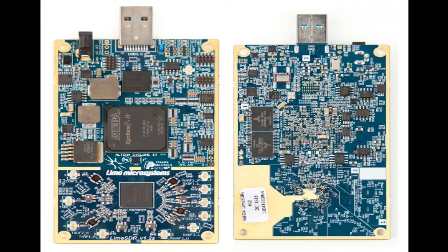It has a lot of other nice features that the Express doesn't have. For example, receive as well as transmit channels, and two of them, and it also has anti-alias filters which are programmable within the chip itself, so we won't need to rely on fixed anti-alias filters like we do at the moment with the DATV-Express board.